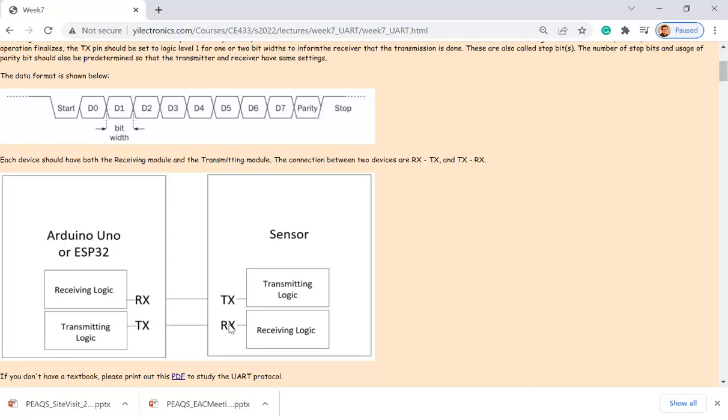Again, just keep in mind, with just 1 wire, if the sender pulls it up, you think you can keep it low here? No, it's going to short the VDD to the ground. So you only have 1 signal. If it's just 1 metal wire, you pull it up, here will be up as well. So that's why you are seeing just 1 line, just 1 timing diagram.